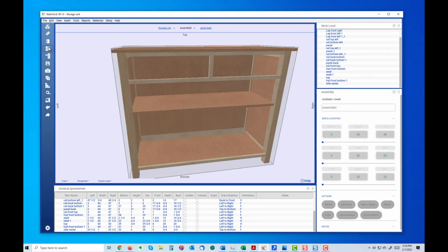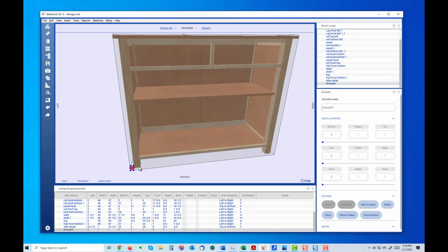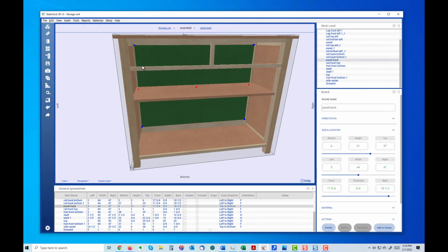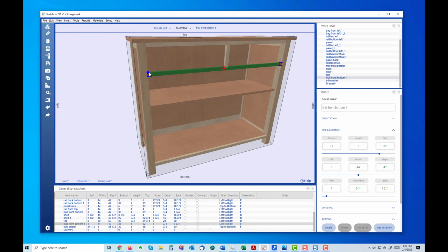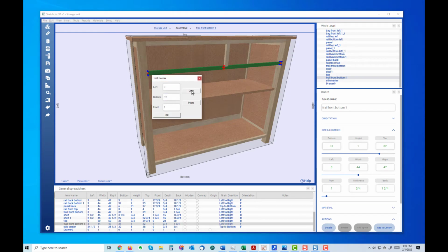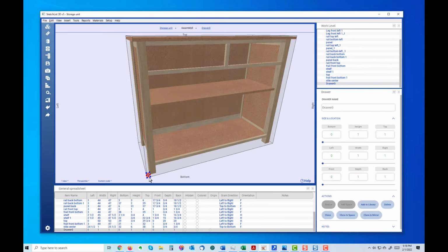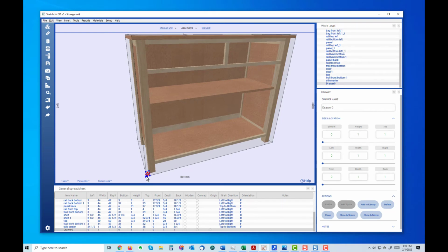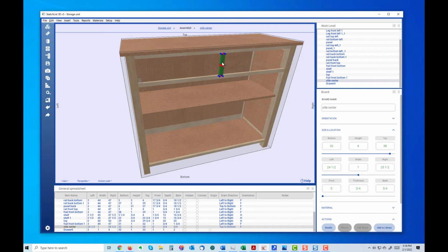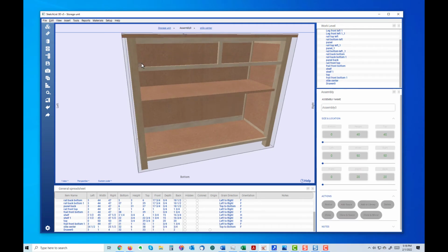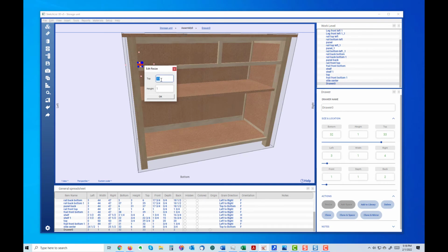Put in a drawer. The drawer comes in, as everything does, in this low bottom left front corner. And another good use of the blue dots. Take the front blue dot value, right click, copy. Take that corresponding blue dot here, right click, and paste. So the bottom of that is 38. So the top of this is going to be 38, like that.